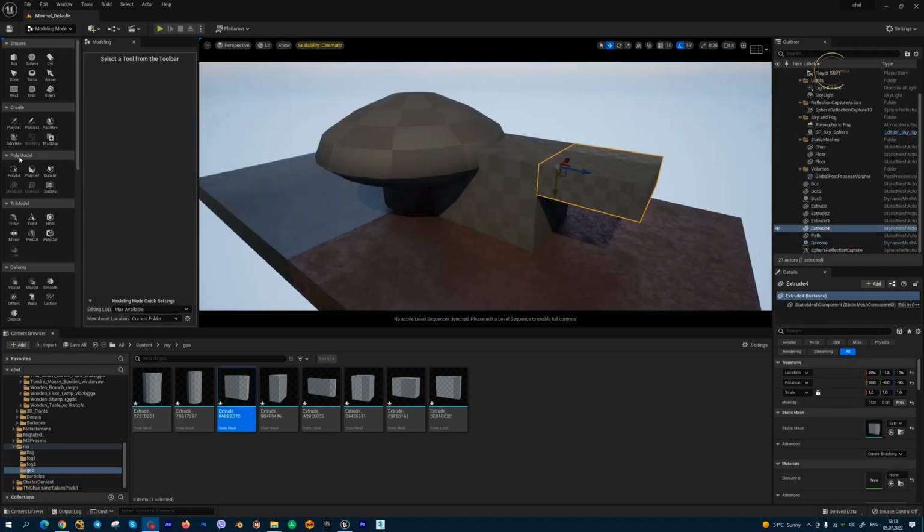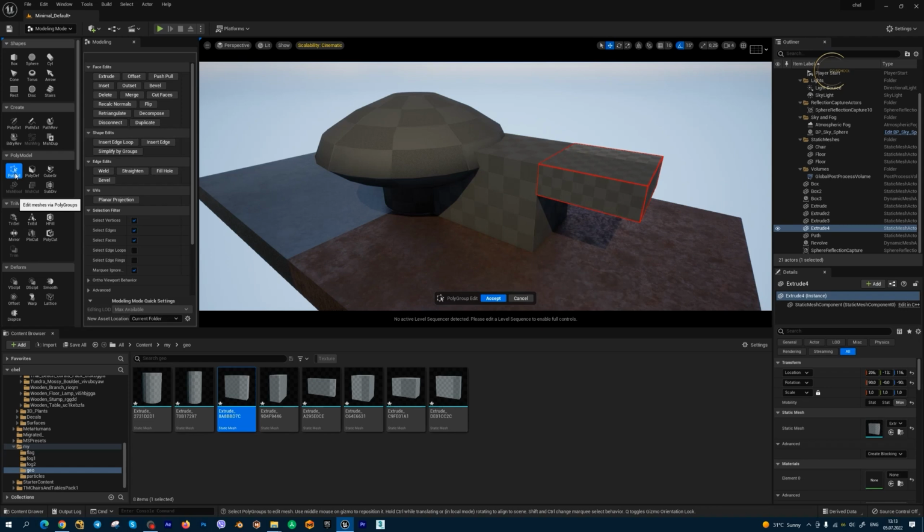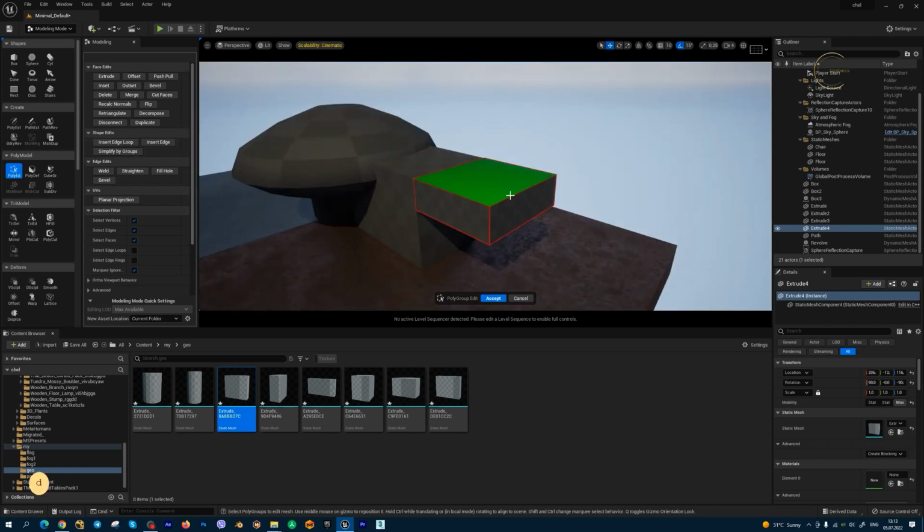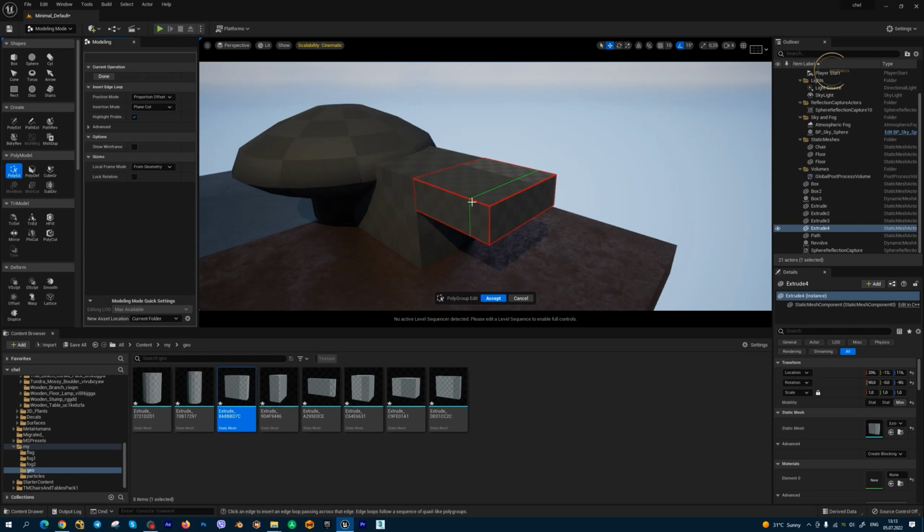The next important modeling tool is poly model. This is not polygon model, this is polygon groups model, and we have the poly add tool inside. Just select this one, and we can work with this geometry. First we can create, for example, edge loops, this one, to make a complex wireframe.